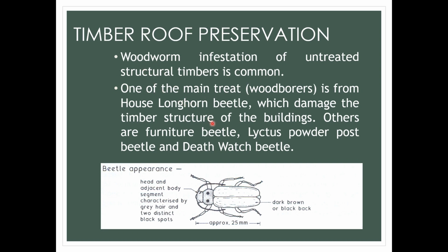So it is very important, very crucial if we use timber trusses. Therefore, we have to get timbers that are treated for woodworms, or preserved timber. So these are examples of woodworms.